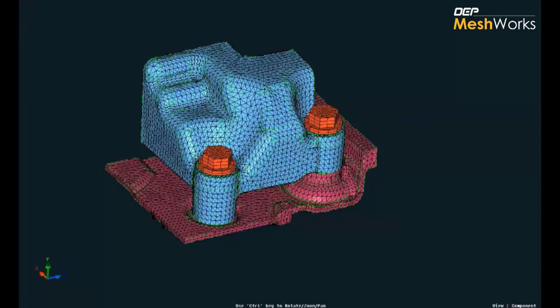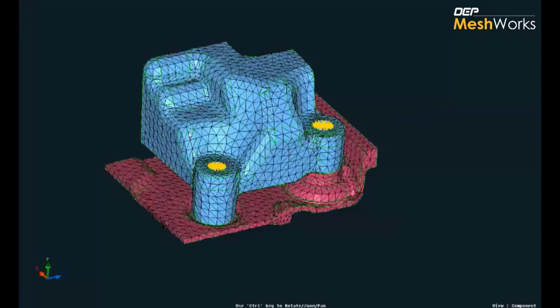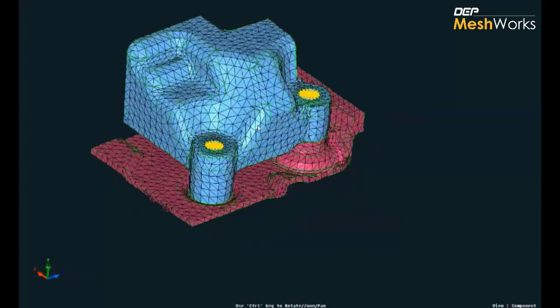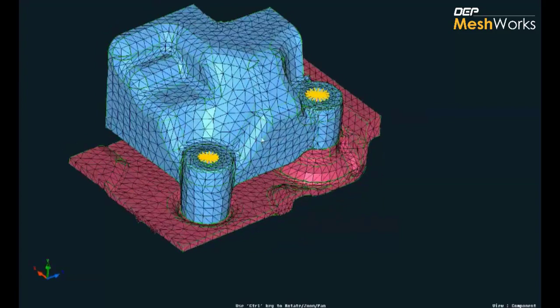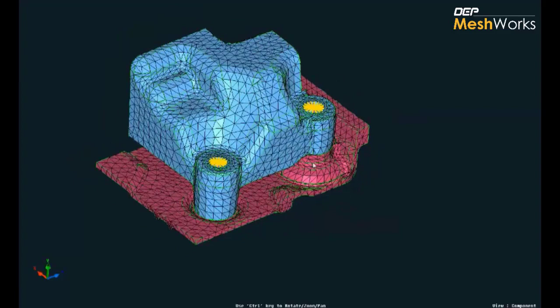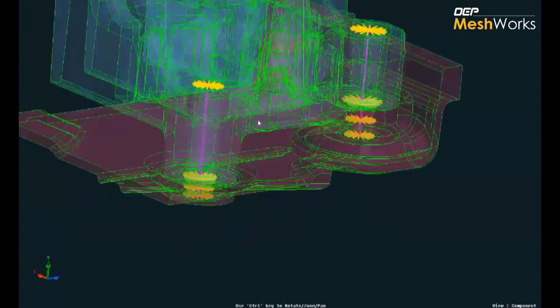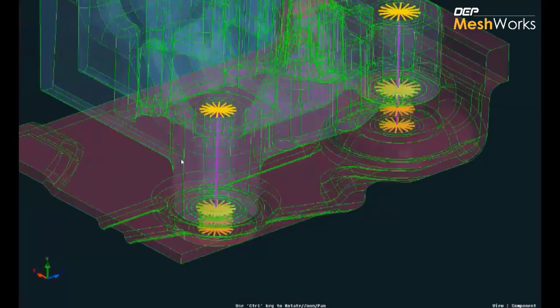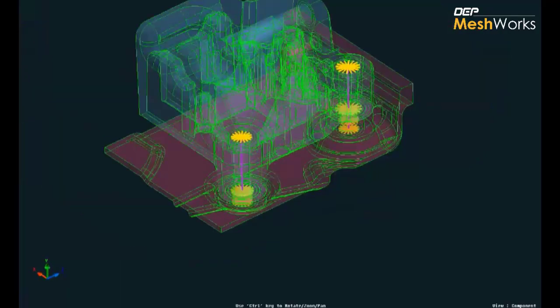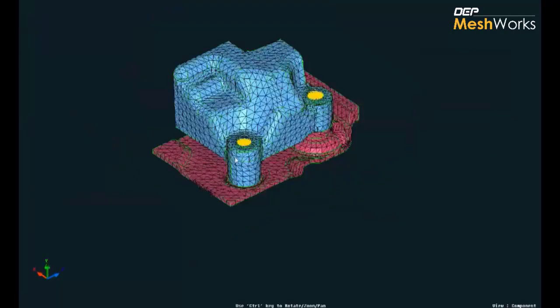So this is actually a very powerful tool. When we are trying to have an entire assembly of components, it takes only a couple of minutes to give all these inputs, and the rest the machine automatically takes care of. Here, as you can see, the mesh is coarser, and the bolt solid connections have been converted into 1D connections as per the Nastran template. The materials, properties, everything has been converted into a Nastran format. So this is one scenario where we can use an integrated modeler.